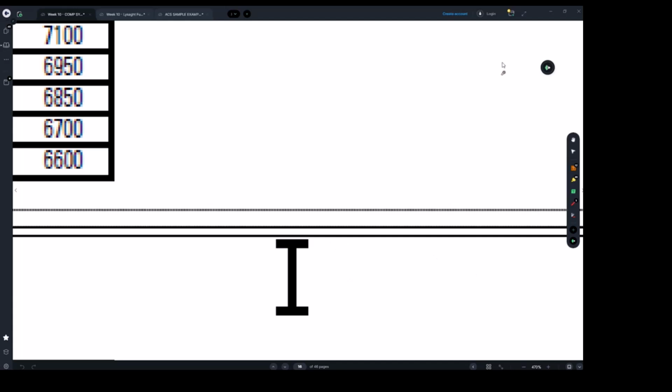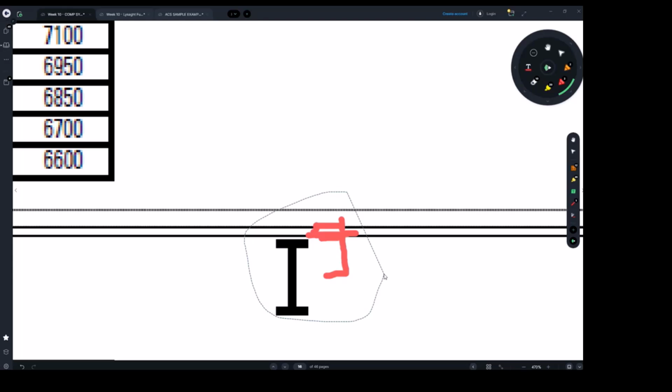If someone asks what if I want to use bonding and I've got just a 200 PFC, then you just weld another plate on top, and that's it. Or use a bigger PFC.